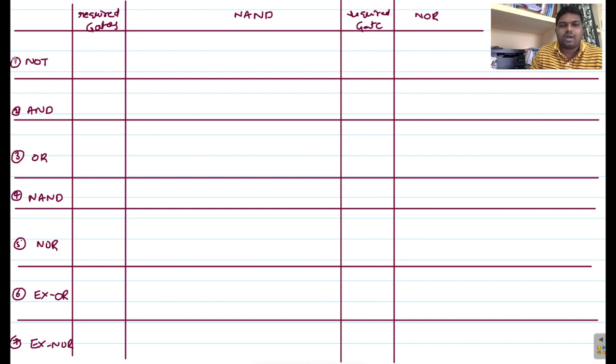These logic gates we can construct with NAND and NOR, these two logics only. With the help of these two logics we can construct all these gates. So that's why we can construct any digital circuit with NAND or NOR logic, right? So first, how you implement this NOT gate with the help of NAND and with the help of NOR. I will explain only NAND gates.